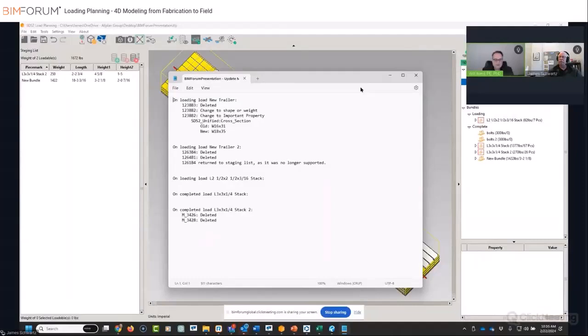Let's say there's a few of the beams that, due to coordination of that MEP space, we want to create web opening penetrations in. We've identified those. That might be an example where we have that beam on hold, because the steel's already been released for fabrication, but we found a few more web openings we wanted to add. How would that work in this workflow?